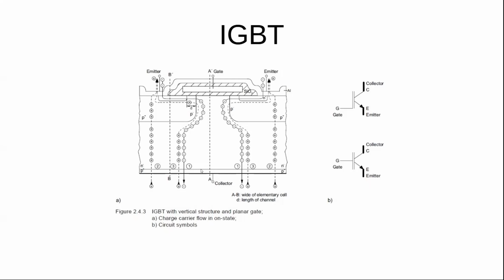So this is actually 4 layers. It's kind of 4 layers in some places, although it's 3 layers on this side, but it's sort of 4 layers for this side. So that's what we have. We just got the MOSFET and added this layer to it, and that created this combination. So we're getting the benefits from the BJT and from the MOSFET.